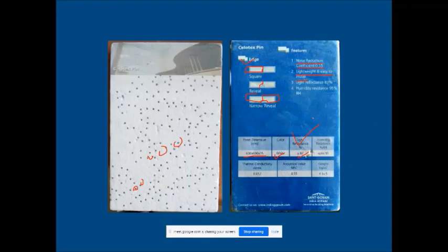By the way, light reflectance is again a very simple term. 82% means 82% of the incident light will get reflected back, right? So that means it will be kind of bright when light falls on this. In case of a library, the ceiling should have around 90% light reflectance. For wall, it should be less than 50%, and for floor or tabletop it should be 30%. You can see the IS code for light reflectance also.